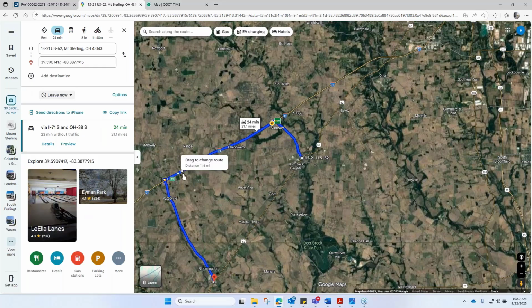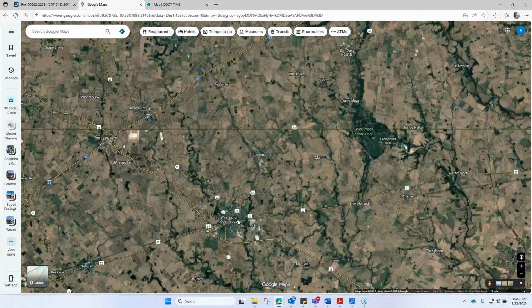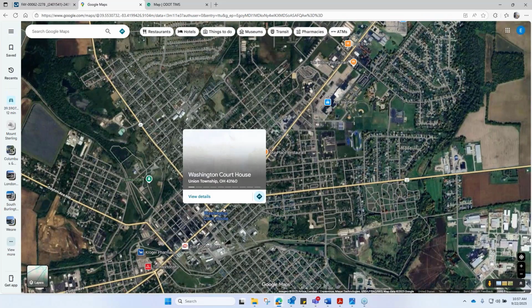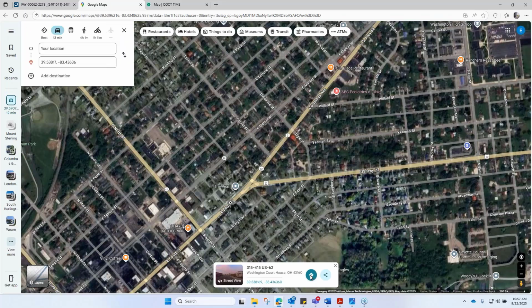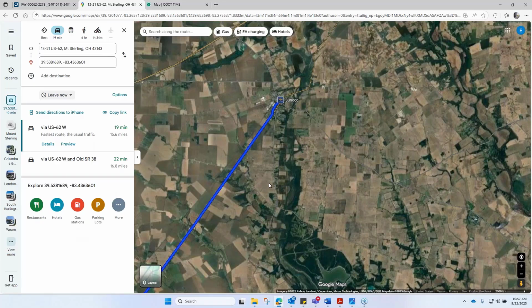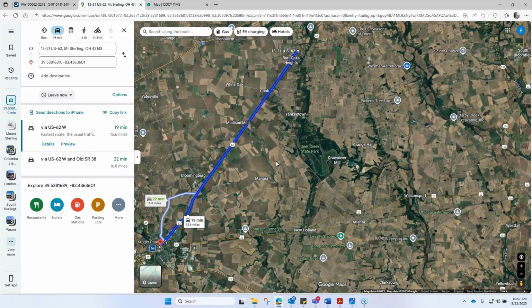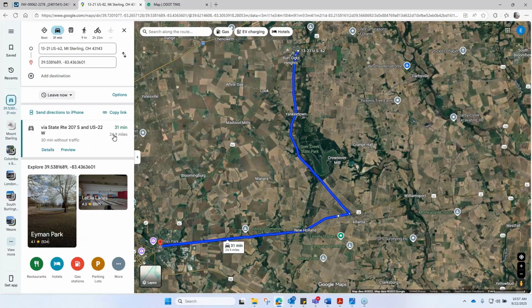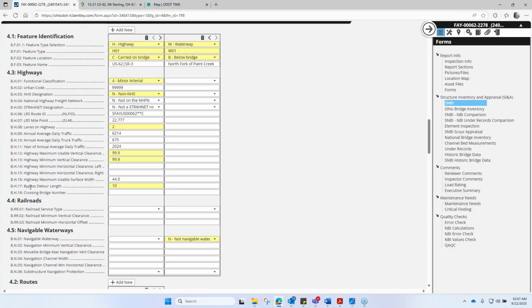So let's check that other one. That other route option starts down here. If we cut them off on 22, it gives us original mileage of 15.5 miles. And then I can again click and drag, and eventually it'll snap into that route I want. Then I can subtract that original mileage from this number, and I'll get about 9 miles. So my bypass detour length is the smallest one of those two, right? So you can actually bypass that bridge in 9 miles.